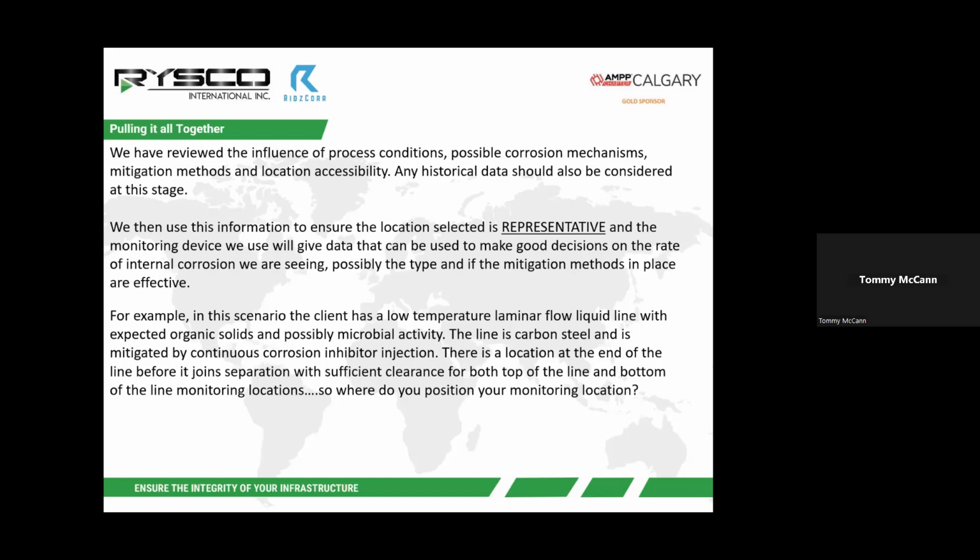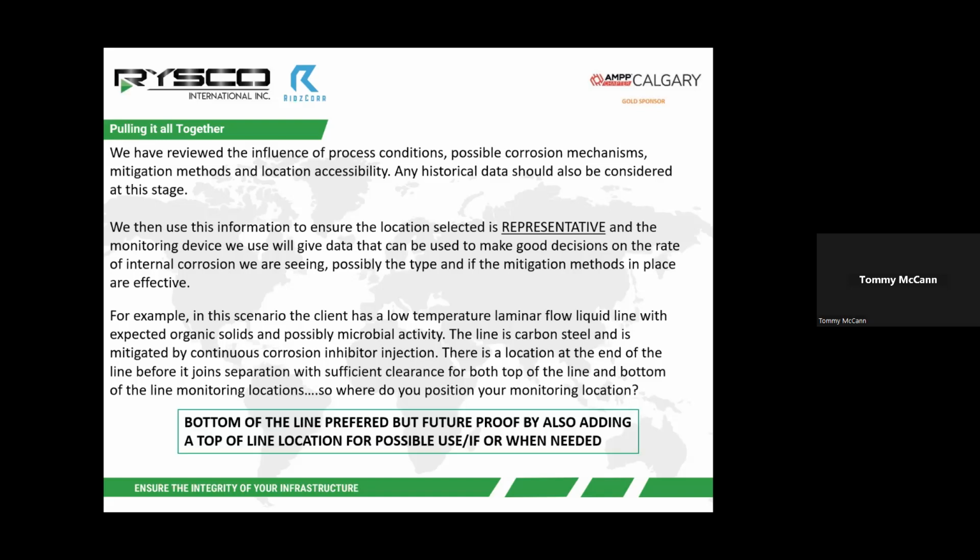So when you pull all that together, where do you position it? My recommendation would usually be, in that environment, bottom of the line monitoring would be preferred. But as you have that spot and you have that potential, why not add a top of the line as well, in case there's a need in the future to measure top of the line corrosion.